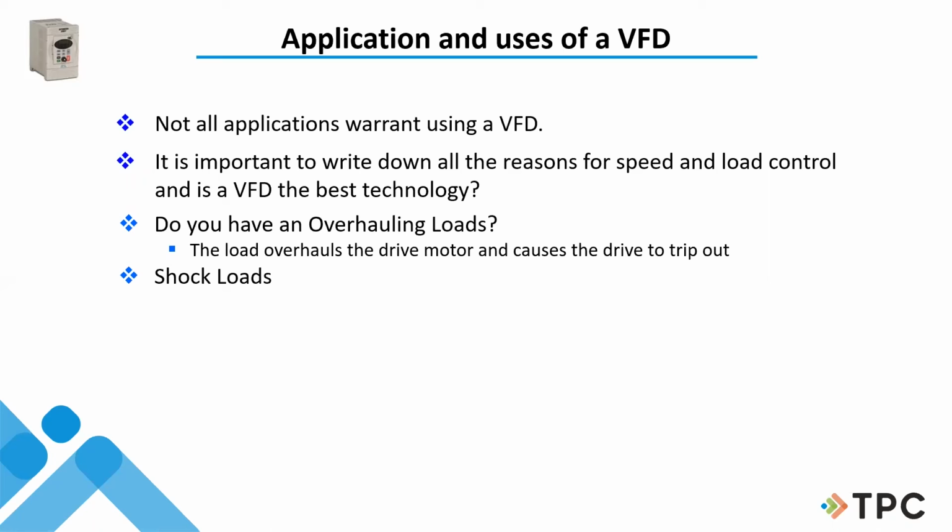Shock loads. A shock load is when, maybe you've got a conveyor running along, and all of a sudden, whatever raw material you use in the facility just gets dumped on it. Well, you can only imagine how much the current goes up for a short amount of time when all that weight gets put onto that conveyor belt. So they call that a shock load. And the drive has got to be capable of handling that additional, high current for just a little bit. Because if it's too much, the drive is going to trip out again. So I need to know if I have shock loads.